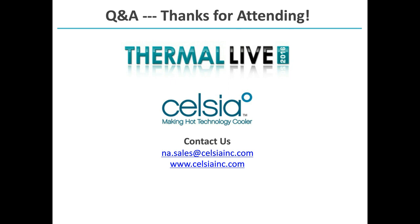Next question comes from Mark Smith. What's a good rule of thumb for derating heat pipe Qmax based on flattening, bending, orientation, etc.? I think we touched on some of that in some of the earlier slides. Bending was about 2.5% loss for every 45-degree bend. Flattening affects more the vapor Qmax than it does the wick structure. So flattening, unless you flatten beyond the wick capability, generally doesn't have a big effect on the performance.